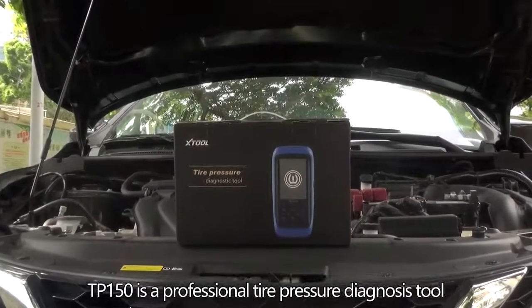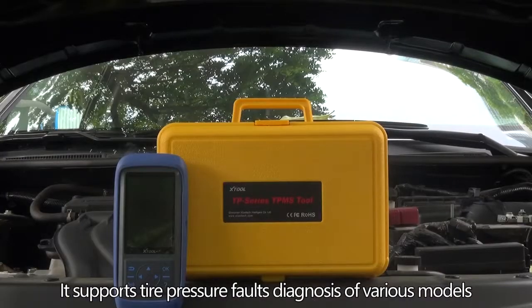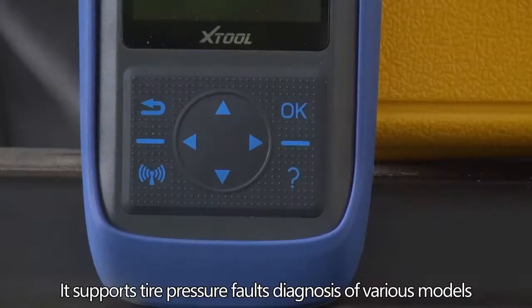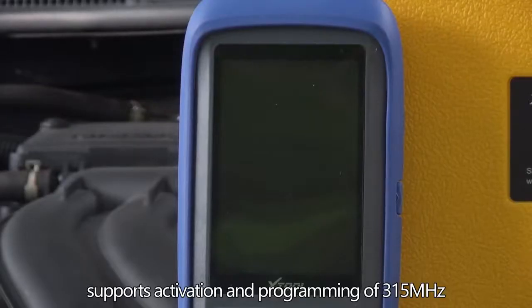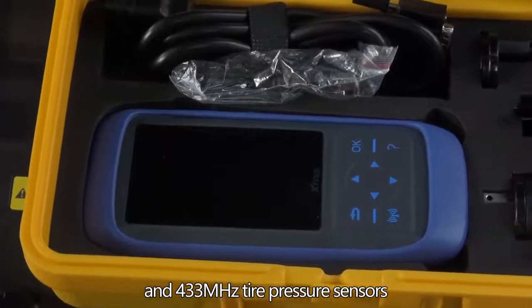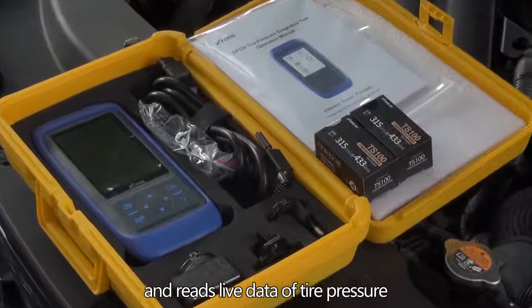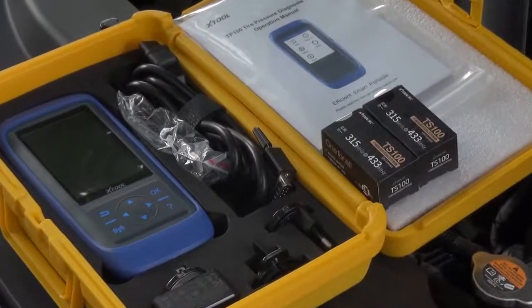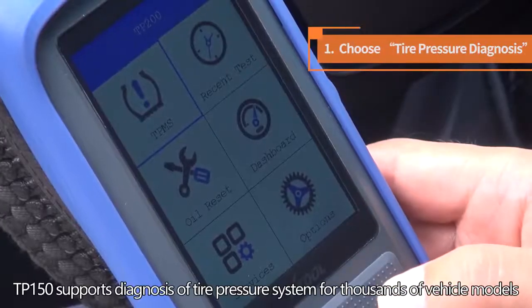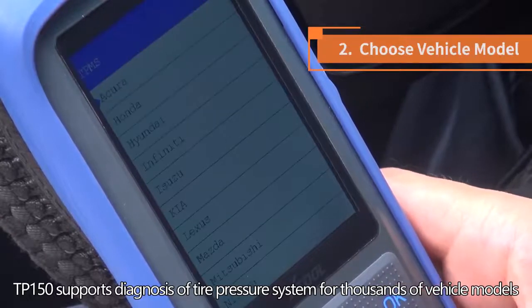TP150 is a professional tire pressure diagnosis tool. It supports tire pressure faults, diagnosis of various models, supports activation and programming of 315 MHz and 433 MHz tire pressure sensors, and reads live data of tire pressure. TP150 supports diagnosis of tire pressure system for thousands of vehicle models.